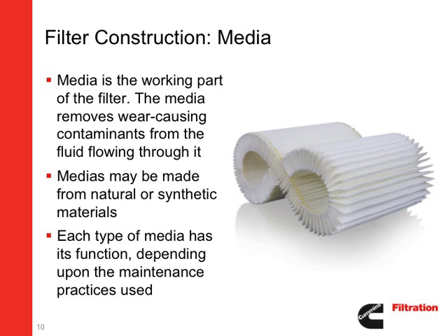The filter element or media is the working part of the filter. It removes the wear-causing contaminants from the fluid flowing through it. Not all media is made of the same material, though. Medias can be made of either natural or synthetic materials. Each type of media performs a different function, depending on the requirements of the application and the maintenance practices used for that application.